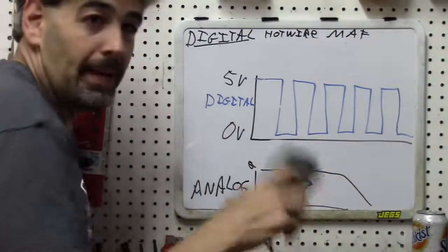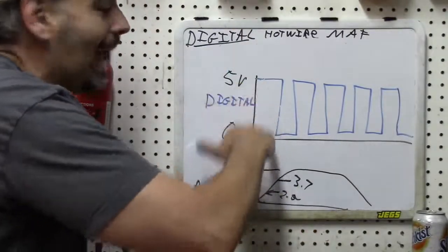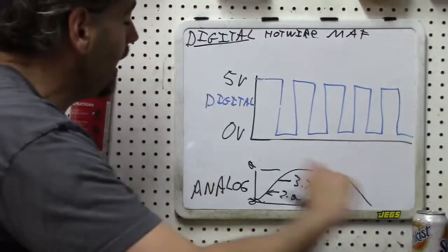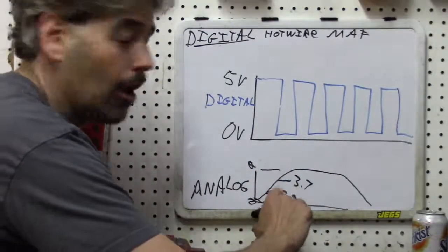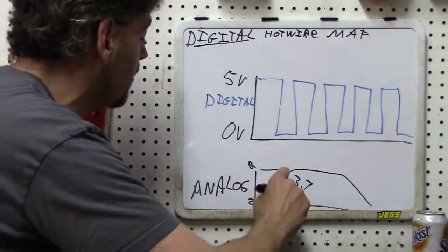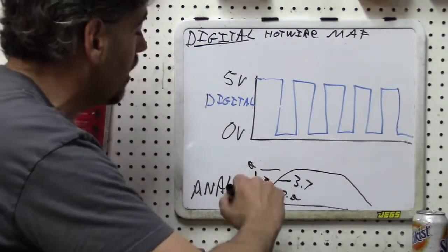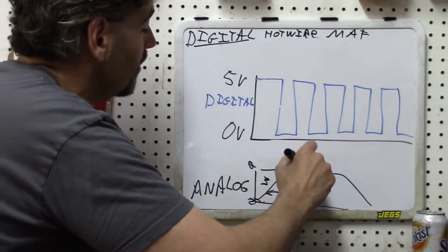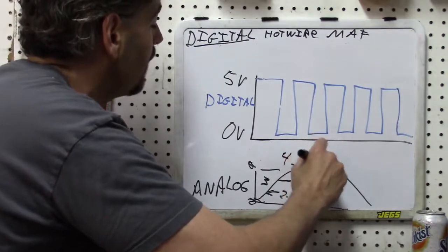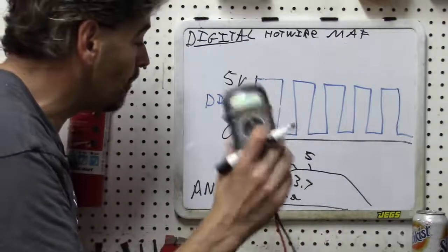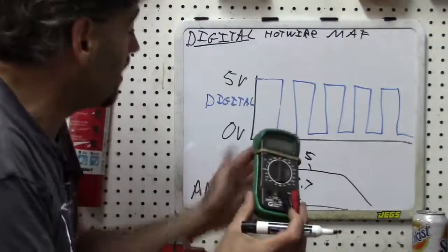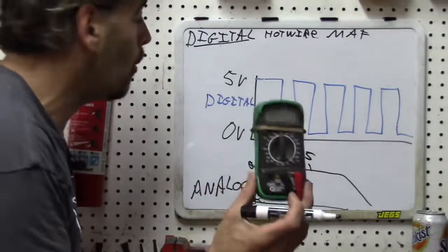So that's a problem, because since your DVOM is trying to take an average of your signals, even on a somewhat faster moving analog, if it takes an average, say, of this 3.7 and 2.5, and it gives you somewhere around 3 on here, and then it reads, again, it's a little bit slower, but it reads up here, and maybe you've got a 4 and up here a 5. So your next reading that jumps up onto your screen is now 4.5. You get to see at least that there was some increase at that point.